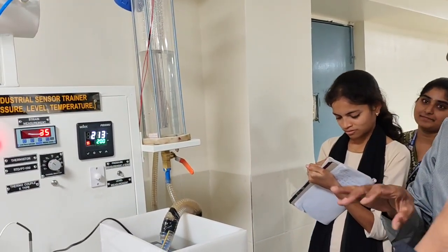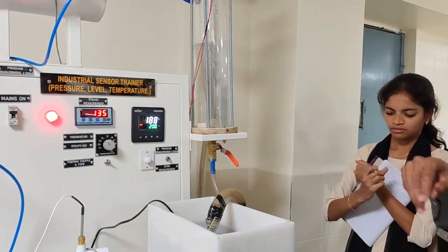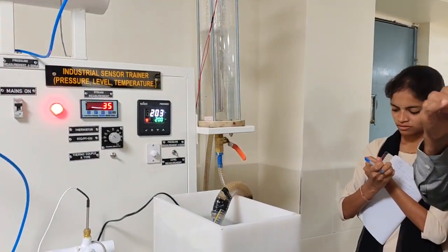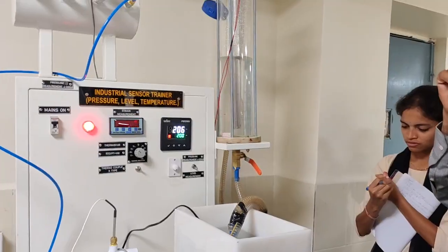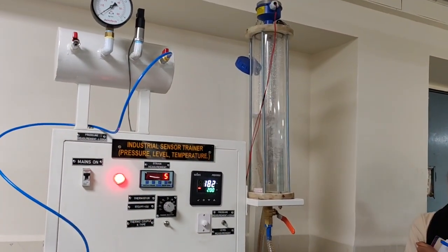In Bhimavaram we have given the same system. You can operate it through the operator. You can set the T value, the DT value, so that this undershooting will reduce and overshooting will come down. 200 will be there, and like that it will operate. Then it will settle exactly at 200 after switch on.